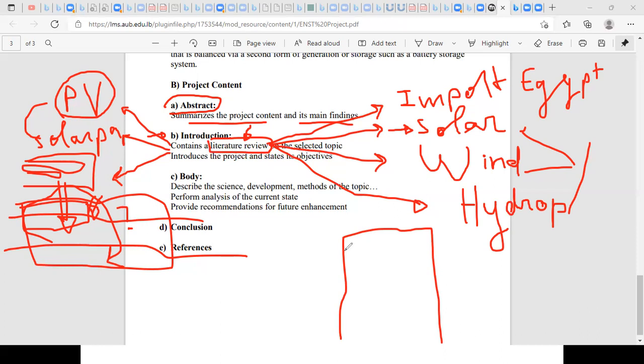Okay, so if I go back to the example of green buildings, you can put several strategies. Let's say I can replace single glazing by double glazing and see how this will affect the total energy consumption in my building. I can change, if you want, I can add a layer of insulation for the envelope.